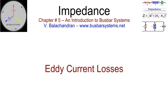Eddy current losses. A current passing through a conductor will develop a magnetic field around it. If the amplitude of the current varies with time, the magnetic field also will vary with time. Any metallic object in the vicinity that is subjected to the varying magnetic field, cuts through the magnetic lines of force, will generate an induced voltage. This induced voltage will cause a current to flow through the metal in a closed circuit. This is called the eddy current.